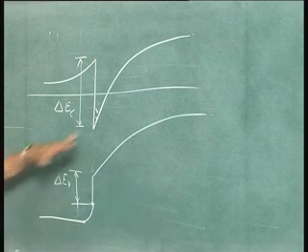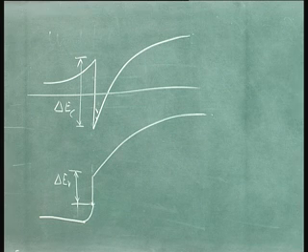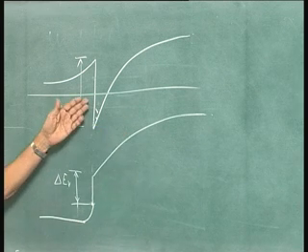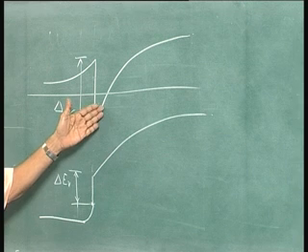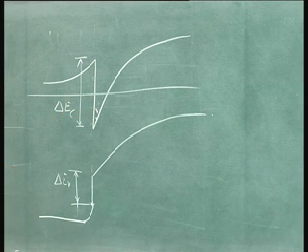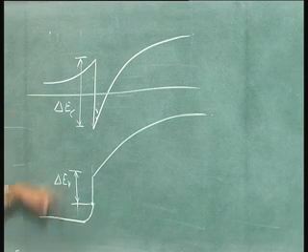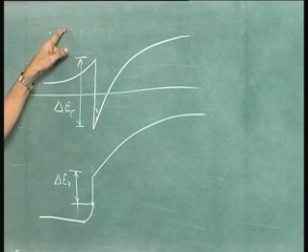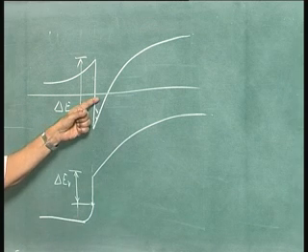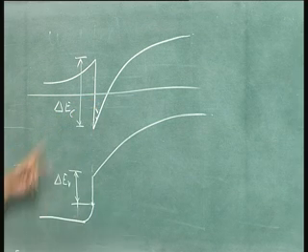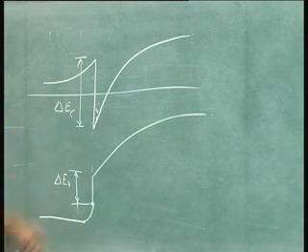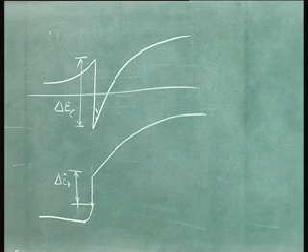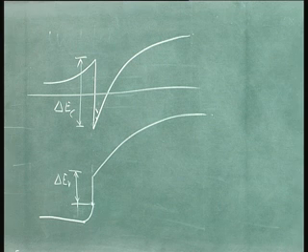So, whatever is happening here. You will see, to start with we had the 3 levels put there, 0 level, conduction band, valence band. Now, here I removed that top level; later on we will remove all this also, because whatever is happening is here. So, delta E c plus delta E v is the difference between the band gaps. One of them if you know, the other follows. In fact, they have measured some of these quantities and arrived at a conclusion that delta E c by delta E g is 0.6 to 0.64.